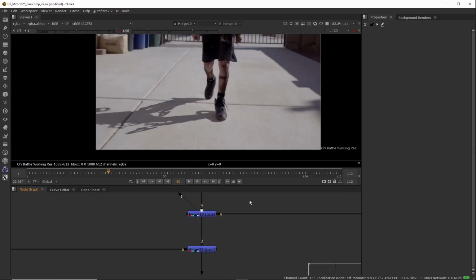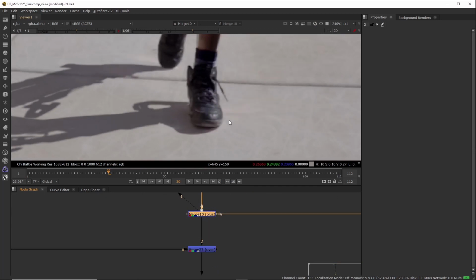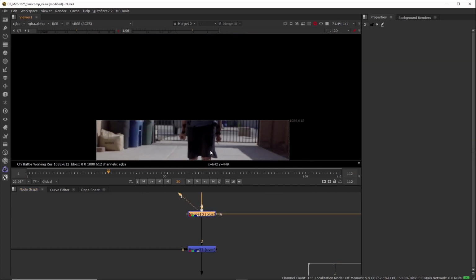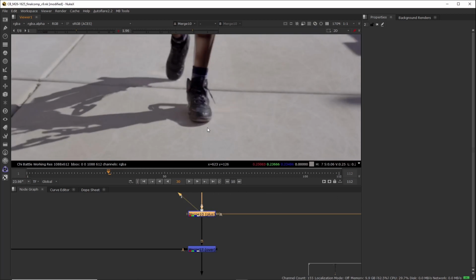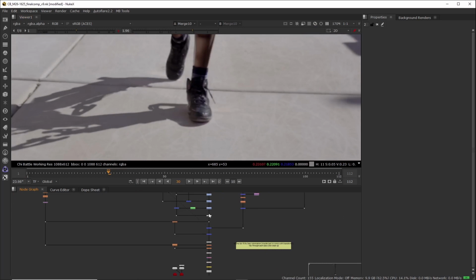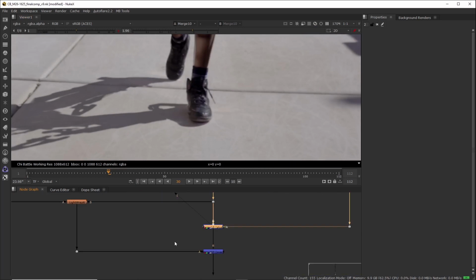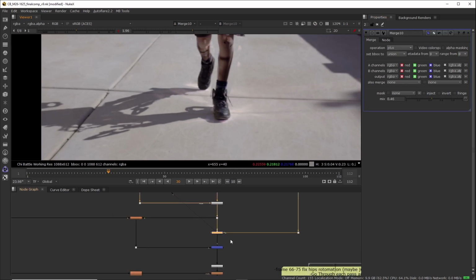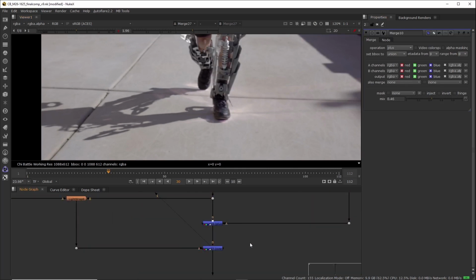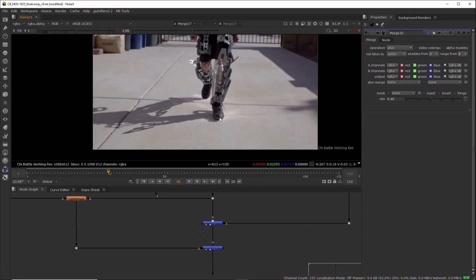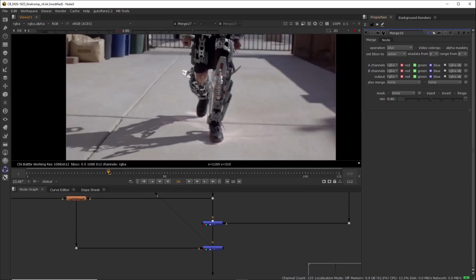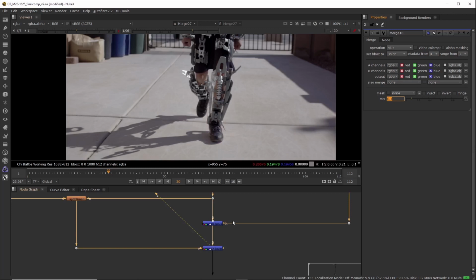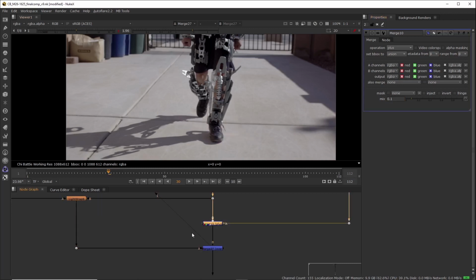So these are the caustics on top, and you can see that I dialed them down quite a bit because I like to keep things subtle. When I think something looks cool, I'll bring it down just a little bit more when I think it looks real, because I try not to go too overboard. I could have easily made this really high and it would have been kind of cool, but I think it would have looked less realistic. As you can see here, that's just way too much light for something as dull as this to throw. So I went ahead and put it at 0.1, and that seemed like a good balance.